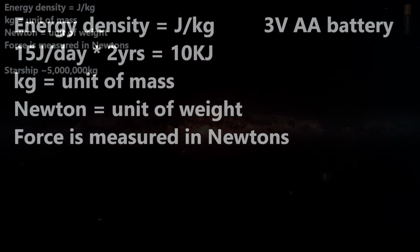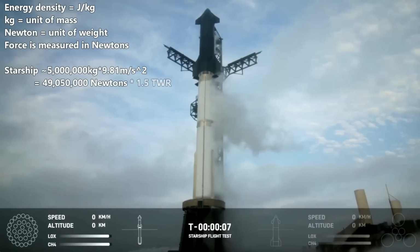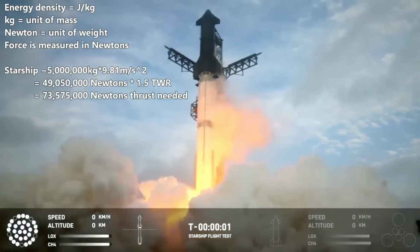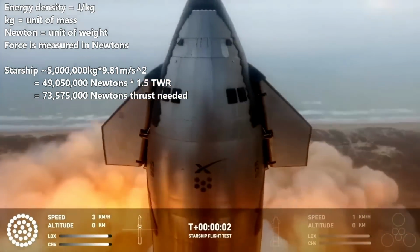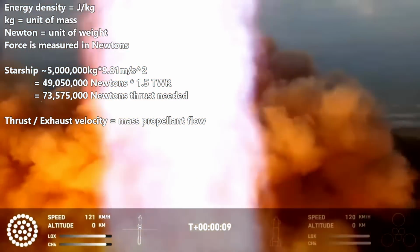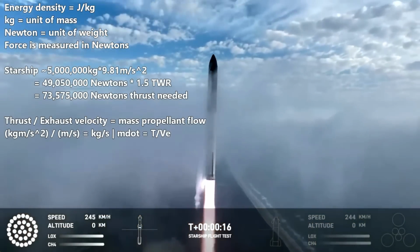We measure our starting mass in kilograms, then multiply by Earth's gravity to get weight, decide on our thrust-to-weight ratio, which, like many ratios, has no units, and get the thrust or force required to launch our rocket. The rocket will accelerate upward, burning propellant as it goes. The amount of burned propellant can be calculated in several ways, but usually we divide the thrust by the exhaust velocity of our rocket engine to get kilograms per second, usually denoted m dot, which is our mass propellant flow.